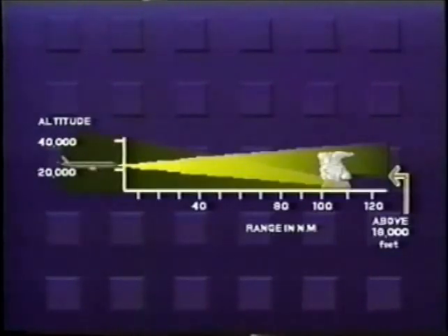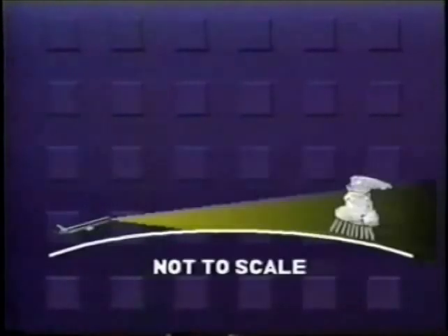At long distances, the energy within the pulse spreads out over a large area. At 100 nautical miles, the beam is 30,000 feet in diameter. That means that at least half of the pulse energy is going to overshoot the most reflective part of a storm. A secondary effect is that, at long viewing distances, the Earth's surface starts to block targets which are beyond about 150 nautical miles. The combined effect of these two factors makes detecting rainstorms at long distances more difficult. If rainstorms are detected at long ranges, say over 100 miles, regardless of their displayed intensity, consider them significant storms and make course deviations as early as possible.